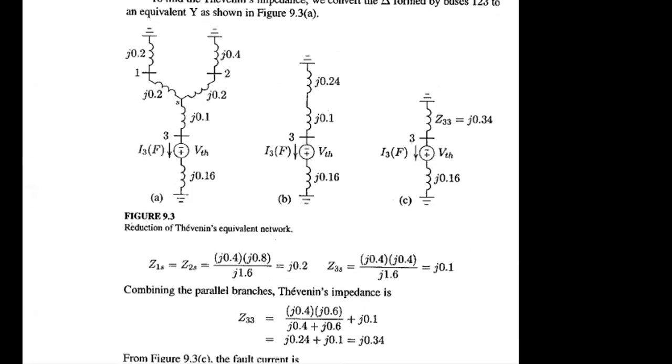When we have I3 current, as we have two generator paths, generator 1 and generator 2, we can get the two generator path currents based on the current divider rule. This is the total fault current, right? I3F. So if we just want to get the fault current in generator path 1, we can find that as well. Can we do that?